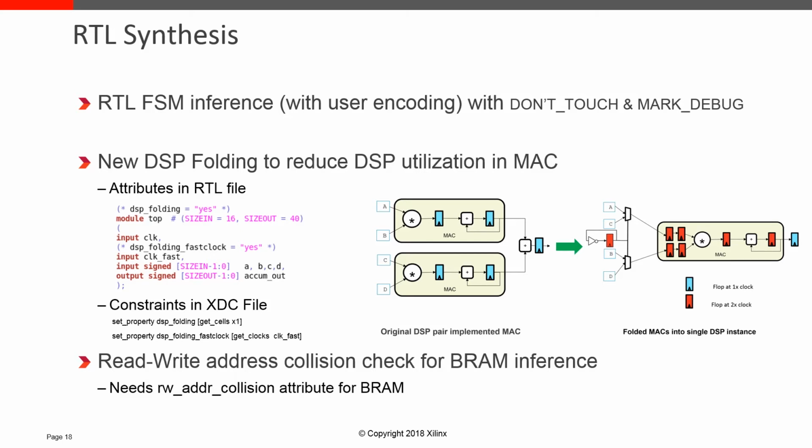The next capability is related to VRAM structures that could be subject to collision issues. As the synthesis tool automatically recognizes them, a new attribute can be set to let the tool automatically infer the extra glue logic to take care of the address collision.